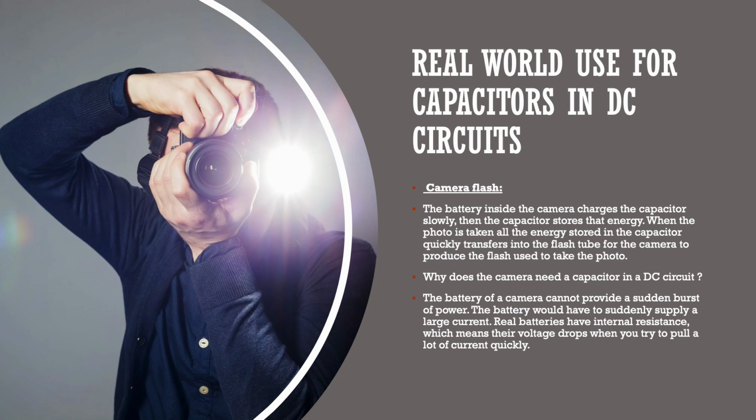Now, I'm going to be explaining the usefulness of capacitors in direct current circuits in real-world situations. We have a camera flash that could be found in phones and cameras. The battery inside the camera charges the capacitor slowly. Then the capacitor stores that energy. When the photo is taken, all the energy stored in the capacitor quickly transfers into the flash tube for the camera to produce the flash used to take the photo.